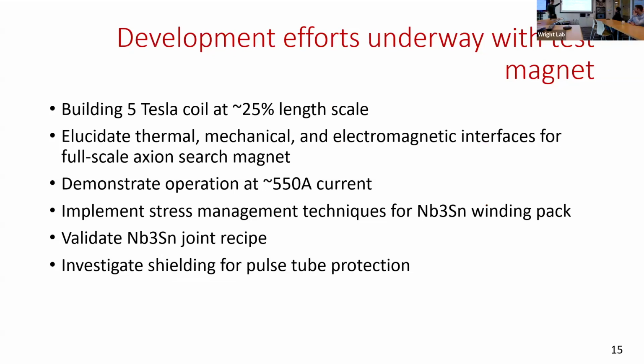Before we build this large bore niobium-3-tin magnet, there's a number of steps that we need to validate and investigate. So we're building a 5 Tesla coil, but it's going to be at 25% length scale. So we're talking about a 200 millimeter bore. And this is really to shake out a lot of the things that we need to know before building a large magnet, especially in the electromagnetic, the mechanical, and the thermal interfaces.